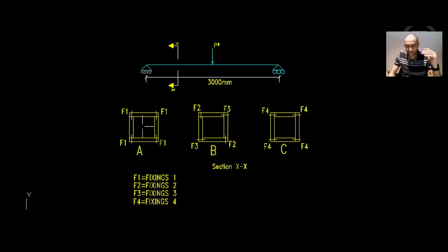The shear stress on F2 are the same because we have 2 horizontal planes passing through the fixings, and it is symmetrical. And F3 in this case is 2 vertical shear planes passing through the fixings. And finally F4, again, they're all the same, because we have 4 vertical shear planes passing through the fixings. Let's talk a little bit about that in details. Now, let's quickly move on to the beam loading and fixing information.